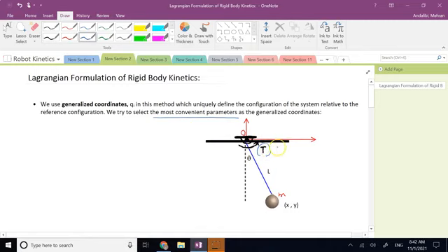So here, the work done by T in general, if T is constant, is going to be T times delta theta, if T is variable, it is the integral of T d theta. And you clearly see naturally that the work of that torque is described using the change in the angle, not the change in position x and y.